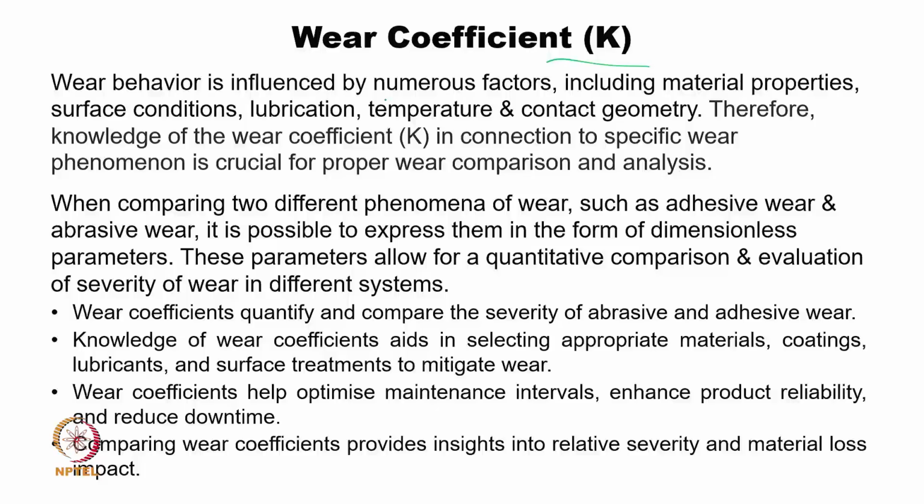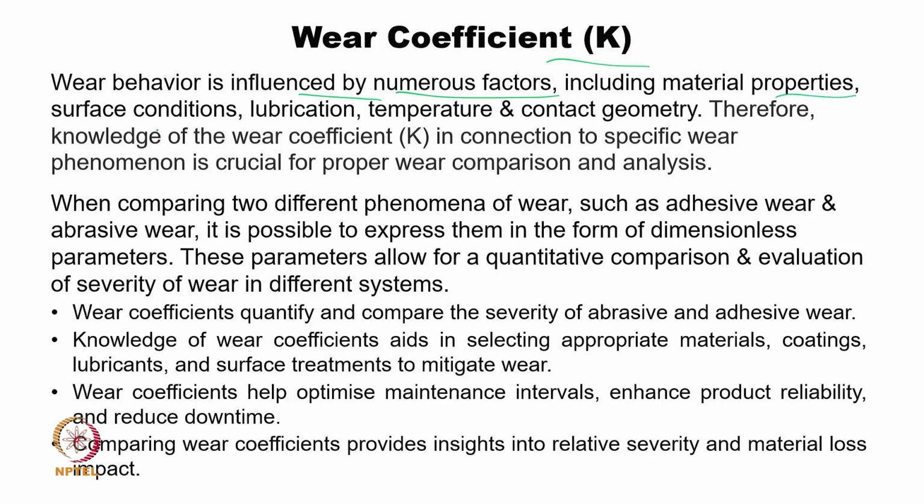Now, wear behavior is influenced by numerous factors, that is what I mentioned, including material properties, surface condition. Even if you change the surface roughness, the wear coefficient will change significantly. Now, change the lubricant, not only lubricant or lubrication, lubricant type also, it will change significantly. Temperature, contact geometry. So, more and more knowledge will always help to really get a solution. Sometimes people feel, oh, there are so many parameters, why shall I worry? I will perform an experiment, that will be more than sufficient.